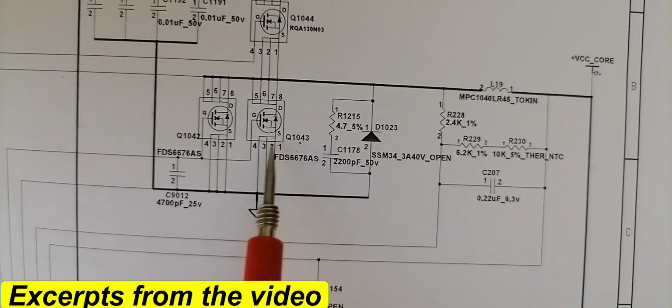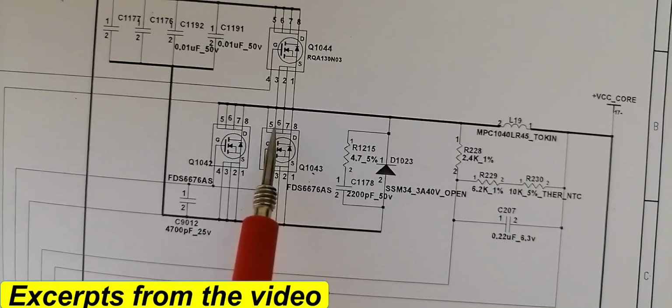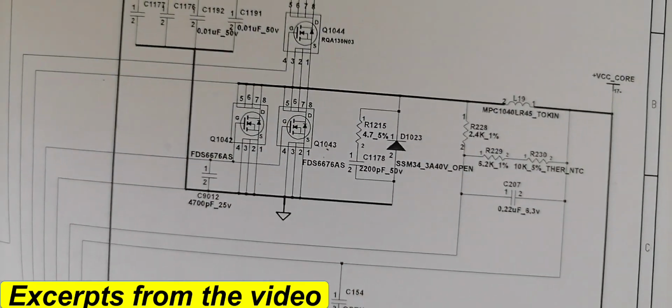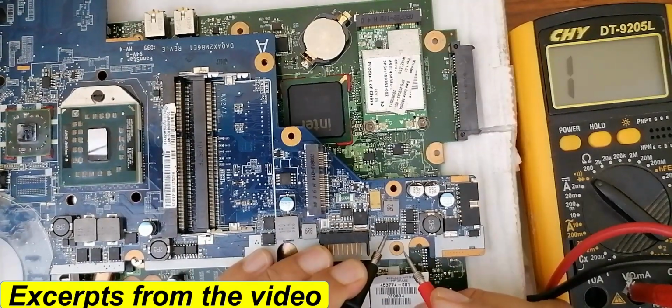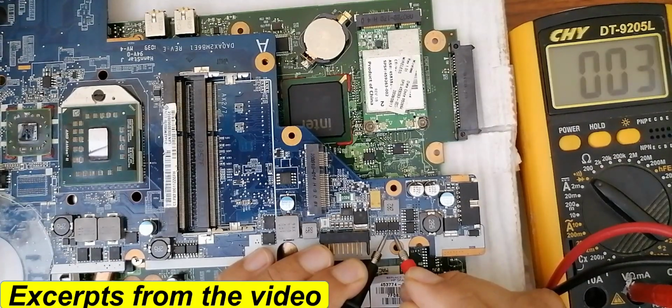Do you see? 1, 2, 3 are connected together. So the other 4 pins for drain should be connected together. So let's check on the motherboard. Let's put this probe on the first pin over here and check with this pin. We get continuity, a beep in the multimeter.